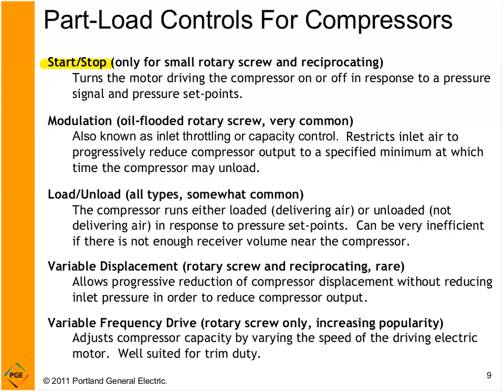Okay, modulation control, or as I like to call it, put a sock in it. If you were to take the air cleaner off your car and stuff a sock down it, it wouldn't be able to draw any air, and the car would probably die. Modulation compressors are very, very similar in that all we do is restrict the air inlet to progressively reduce the compressor output. There's a valve that closes, creates a pressure drop, and the compressor just doesn't have the air to bite into. Hence, it doesn't go out. So that's how we can modulate or vary the flow through the compressor.